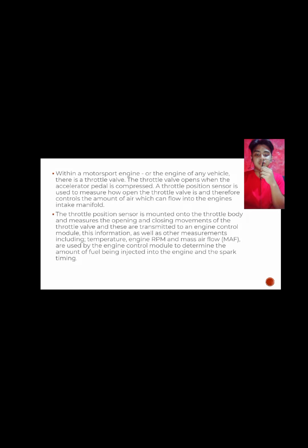The throttle position sensor is mounted into the throttle body and measures the opening and closing movements of the throttle valve, and these are transmitted to an engine control module. This information, as well as other measurements, including temperature, engine RPM, and mass airflow (MAF), are used by the engine control module to determine the amount of fuel being injected into the engine and the spark timing.